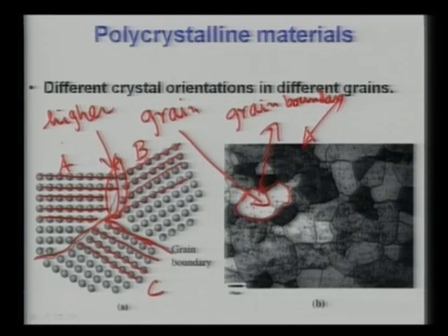This brief understanding is required, because later on I will mention grains and grain boundaries very often to describe the microstructure of different materials. Now the second important thing in this microstructure is that this particular scale bar is around 100 micron. From this scale bar one can understand the typical size of these grains. If you take a particular diameter of this grain, it will be roughly 1.5 times the scale bar, so it will be likely 150 micron.